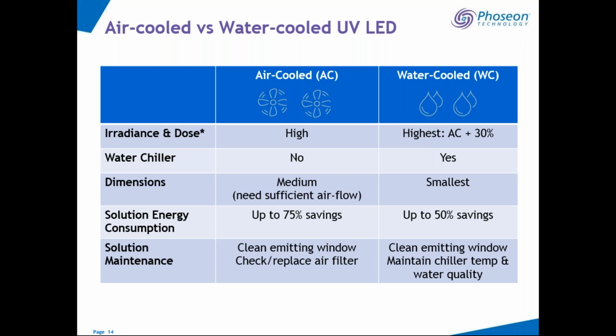And then finally, maintenance is much simpler with air-cooled in this marketplace. You just have to make sure that you're cleaning the window on both sides, but also changing the air filter, versus monitoring the chiller temperature and water quality that we find on water-cooled. The nice thing is that both solutions are in the marketplace. Many providers are out there for these UV LED solutions, whether it's water-cooled or air-cooled. Phoseon is seeing that many of our customers are moving in the direction of air-cooled, but we do have water-cooled offerings as well and continue to lead that marketplace.